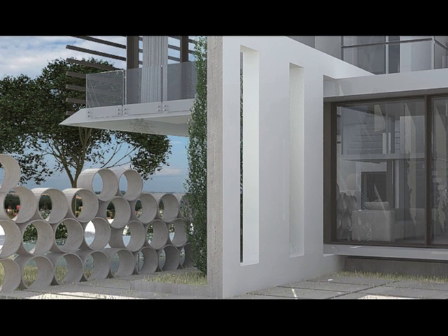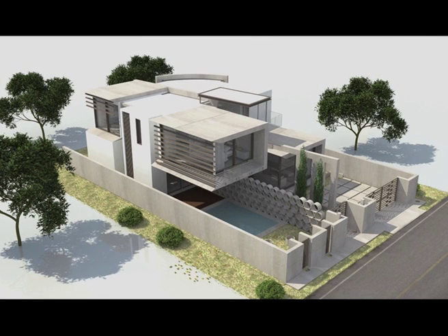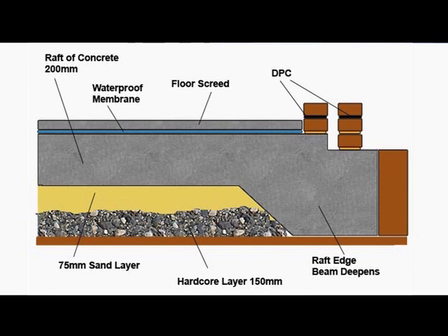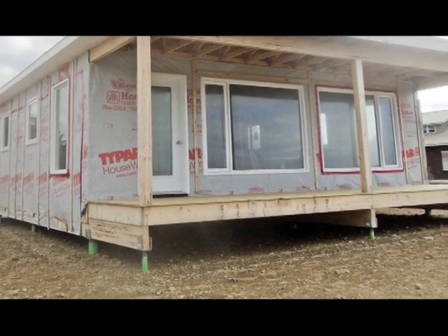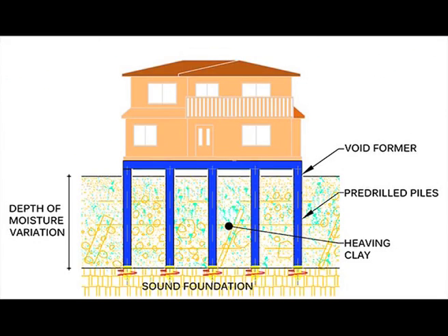You see, the type of superstructure, house or building, as well as the soil condition determines the type of foundation design. With regards to soil report, the soil report indicates what type of soil we are dealing with. If we're dealing with a softer soil, we will generally use either a wider raft or pad foundation, and when we move to soils that cannot hold the superstructure, we will go with a pile foundation, which is a lot deeper, which then spreads the load of the superstructure deeper down. So that's basically how a soil report will help the engineer choose and determine what foundation he wants to use.